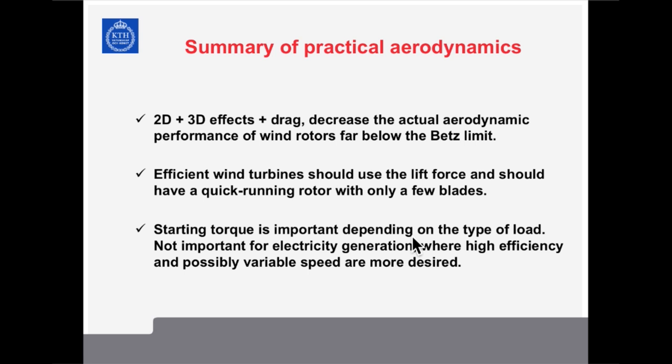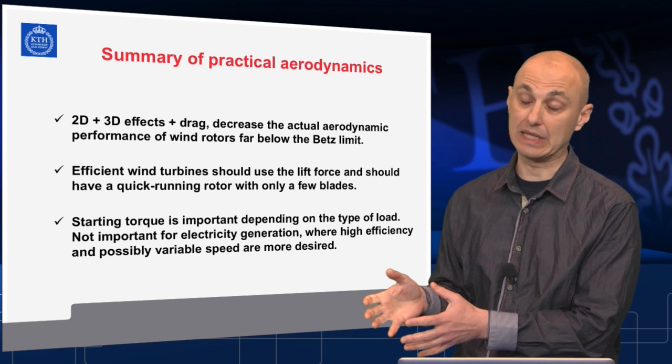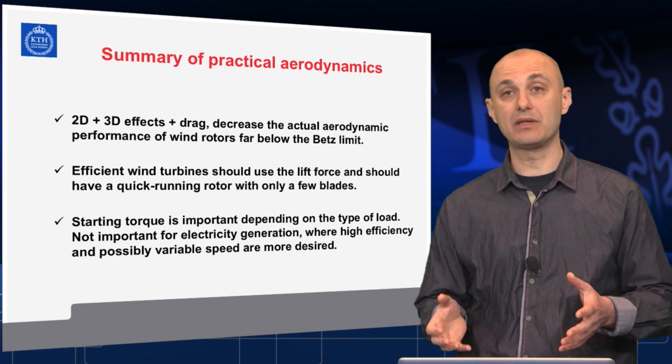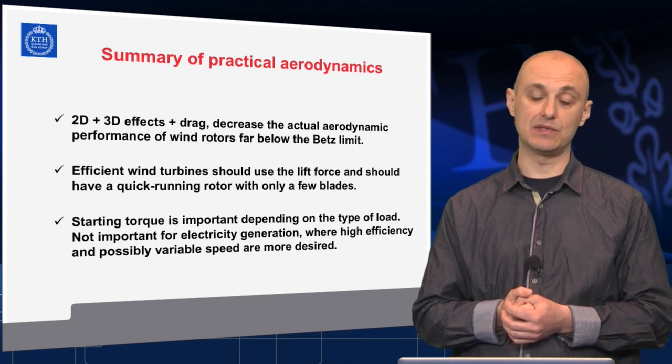Starting torque is important if the device is supposed to operate constantly loaded, and if it should be able to start on the load or to start up from standstill while the load is constantly connected. This is the typical case of a wind pump. We are coming back to those turbines later on.